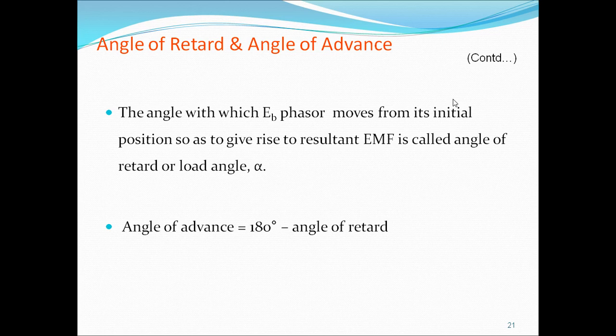The torque produced at the time of starting, that is at the initial time, is called starting torque. The torque produced during running condition is called running torque or load torque or simply torque. The torque produced when the rotor poles are pulled into synchronism by the stator poles is called pull-in torque. So how many torques have we understood now?